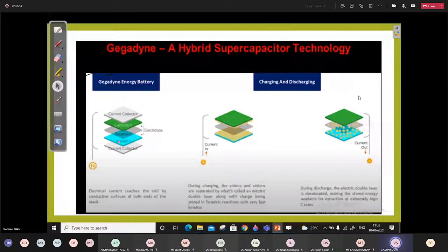And when you are providing regenerative braking, your torque becomes negative. At the same time, if you see here, your current also becomes negative. So this is the mandatory requirement to implement regenerative braking: the motor should supply current, not draw current, and that's why the current should be negative. If current is negative, then definitely your torque becomes negative, and that will implement the regenerative braking.